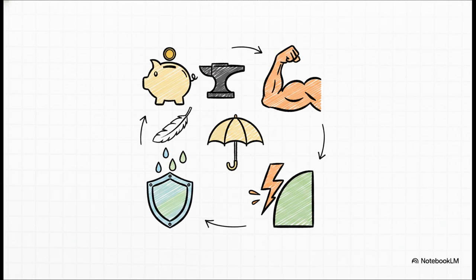Plastics have replaced traditional metals and ceramics in countless applications, and it's mainly because of plasticity, meaning they can be permanently deformed and molded into shapes using heat and pressure. Plus, they cost almost nothing to fabricate. They have incredibly low densities, meaning they're super light, which makes transporting them a breeze. Yet, despite being lightweight, they still possess incredible mechanical strength. Add to that the fact that they don't rust like metal, they're highly resistant to corrosion and moisture, and they serve as fantastic thermal and electrical insulators. It's a pretty unbeatable combo.